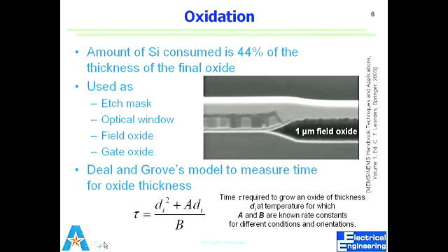So we cannot use glassware to hold BHF, because it etches glass, it etches silicon dioxide. So we have to use containers made of what? Plastic? Teflon. A special type of polymer. A special kind of plastic. Teflon doesn't really get affected by BHF.